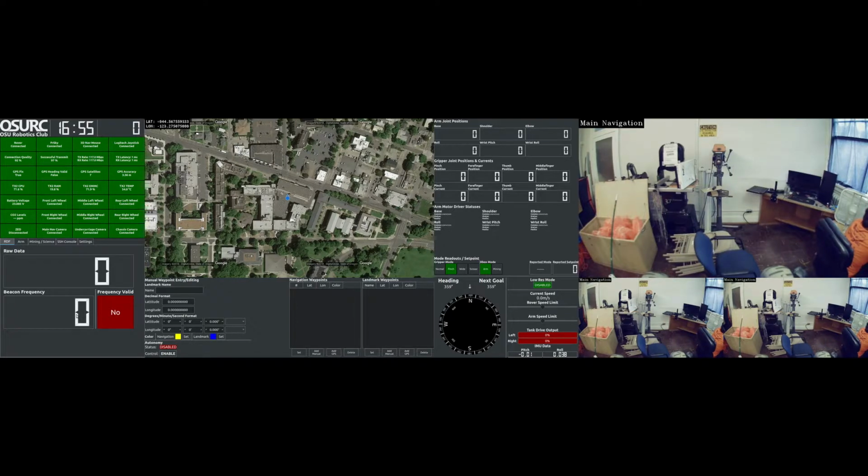This should bounce around when the data is flowing normally. And once it's stabilized and it's gotten a frequency that's relatively stable, frequency valid will turn green and say yes, and you'll know that this is actually valid. At competition, we were finding a signal that was exactly a hertz, pretty much bang on, like maybe 0.999, but very, very accurate.